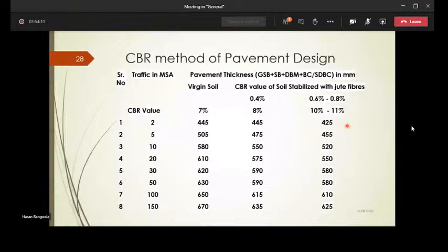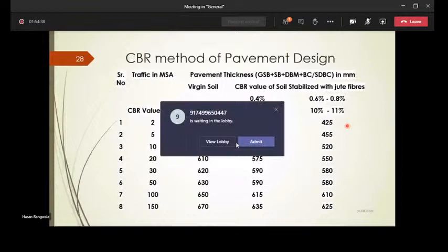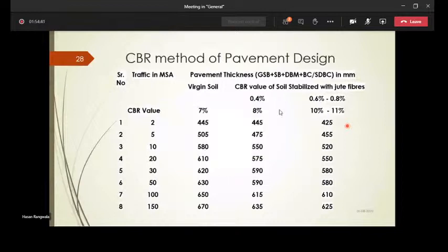The soil I selected was marine clay, which consists of more silicon dioxide. What is the fine content of the soil? Percentage finer than 0.075 mm; my sand and silt particles are 98 percent. So you do not have more of the fine particles; rather, you have the sand only.